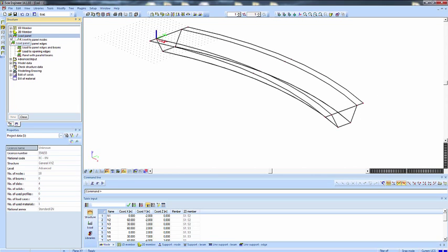Load panels are more used if you have, for example, a steel structure with steel elements, or just a type of structure without any plate elements, but you do want to use surface loads. Then you can use the load panel, which catches the loads. Like for example, having a steel hull with a lot of windows. Then you can use load panels, which take loads just like your windows would, for example wind. But load panels do not contribute to the total stiffness.